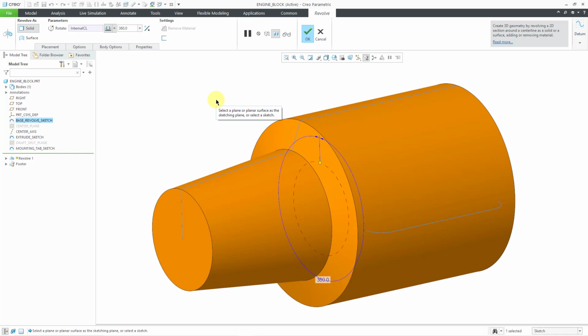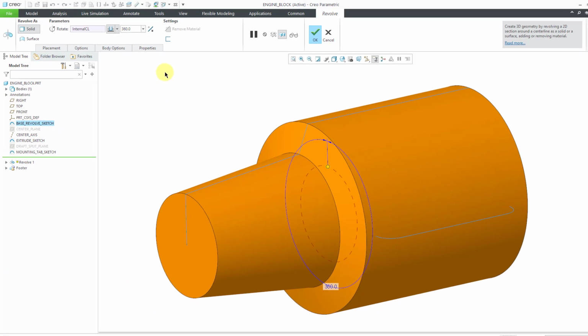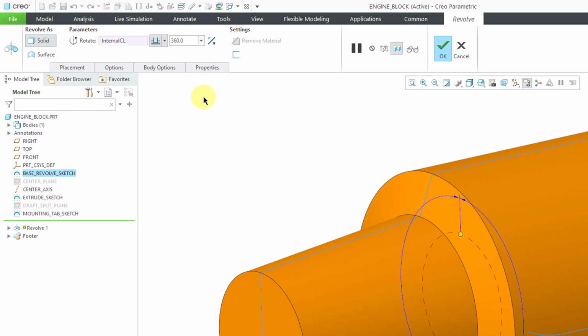Now here is a big difference if you're coming over from SolidWorks. When we were in SolidWorks, we were getting the property manager on the left-hand side of the screen. In Creo Parametric, you get an interface that's called the dashboard. Why is it called the dashboard? Well, when Wildfire 1.0 first came out, over 20 years ago, it was down at the bottom of the computer screen, and so it was meant to be a dashboard, but they found that people were moving their neck too much, and so they put it up at the top of the screen, yet they still call it the dashboard.